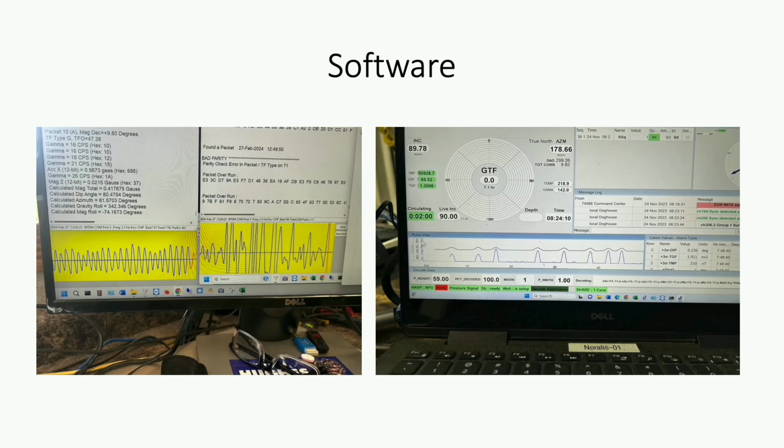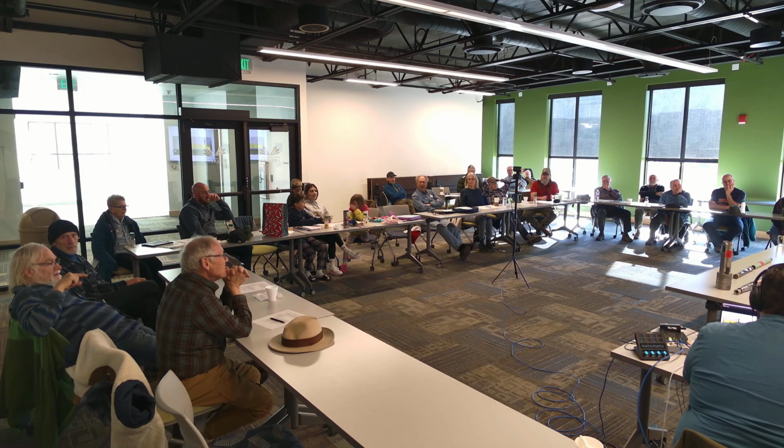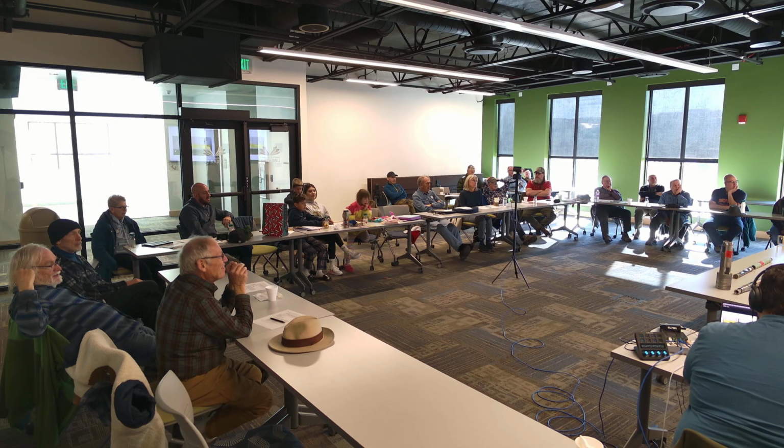Especially thinking about where sometimes your tools will fail. Yep, yeah, it's pretty common. They will always fail. And when that happens, is it the same as a bit failing? Or can you put two units down and have redundancy? You can do that. Most of the time we don't, because the farther you get away from the bit, the harder it is for us to calculate and make real-time decisions, because we have to make projections to the bit all the time. If we're 80 feet back, that's not ideal. Ideally, we'd want to know where we're at at the bit at all times, but we can't do that.